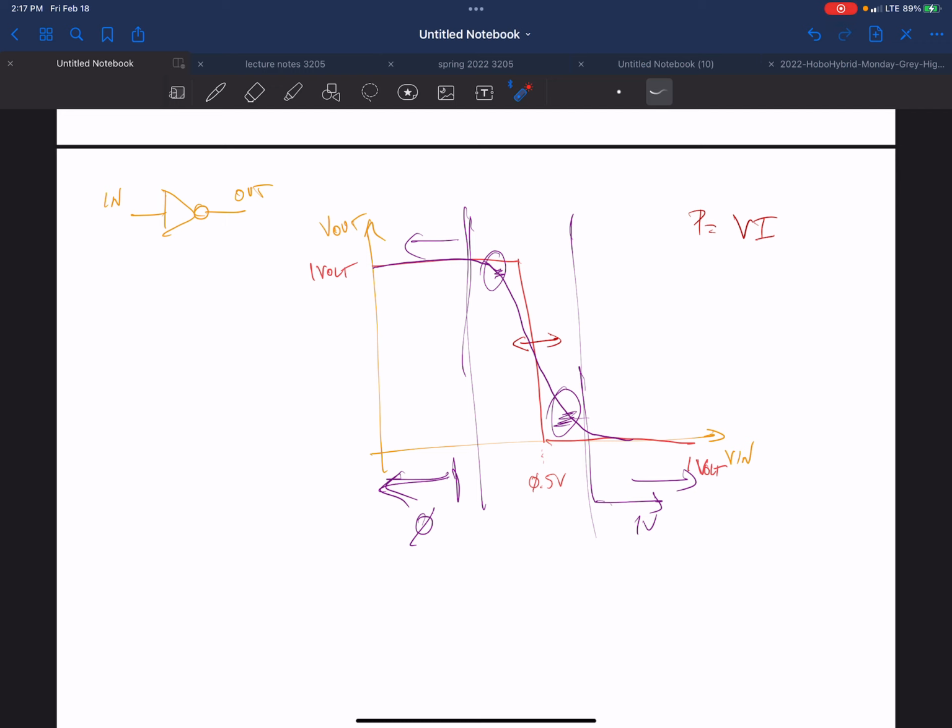By the way, this whole thing about supply voltages is another reason, and we'll talk about some other stuff, why power supplies are stuck at about 1 volt or 0.9 volts. For a while, we went from 3.3 volts to 2.5 volts, 1.8 volts, 1.3 volts, but generation after generation of processes right now, a 45 nanometer process has a 1 volt supply, and a 28 nanometer process supplies 1 volt.